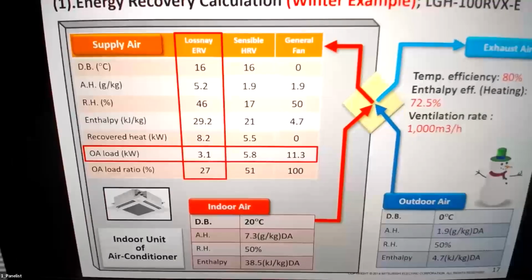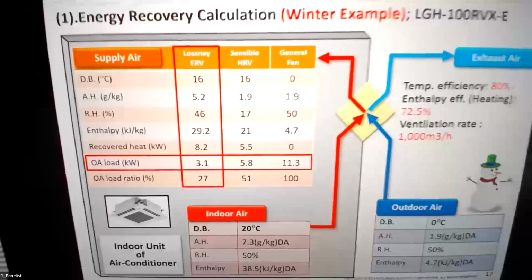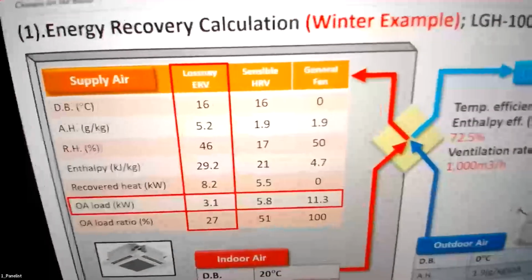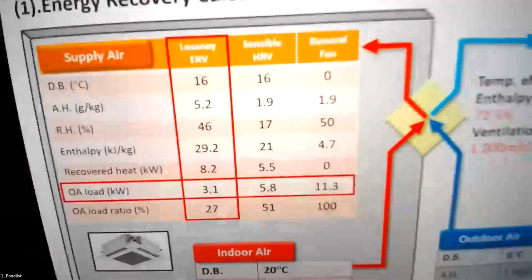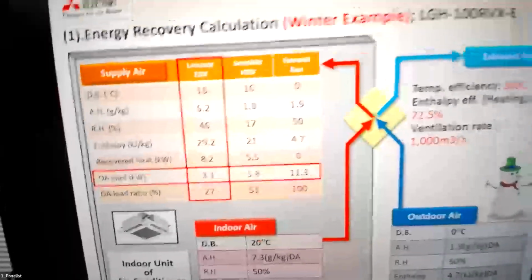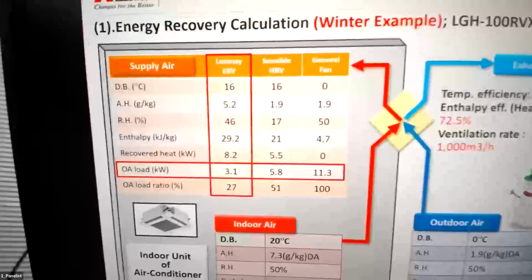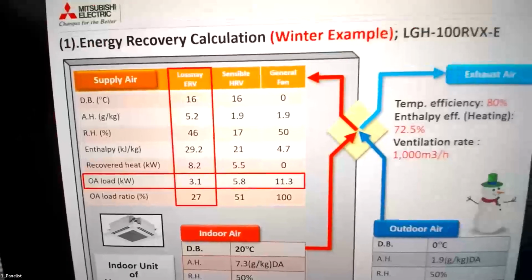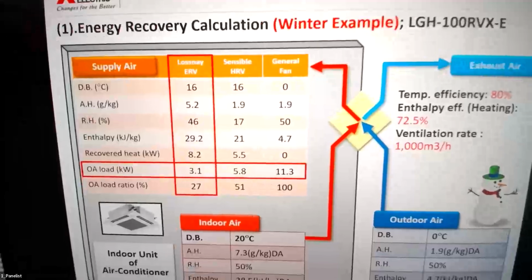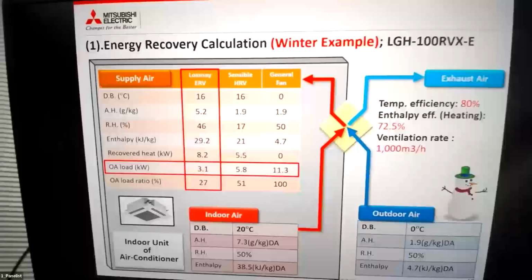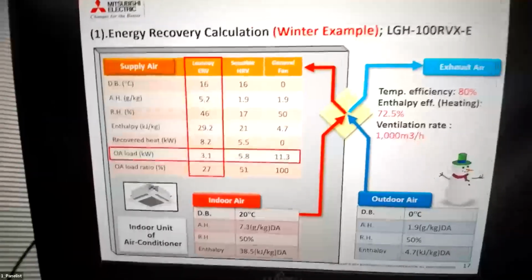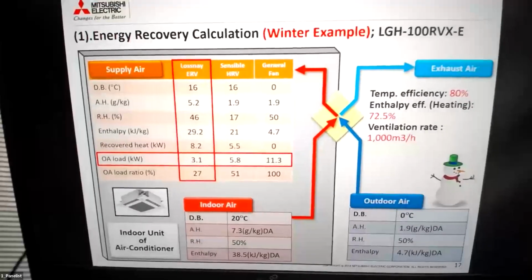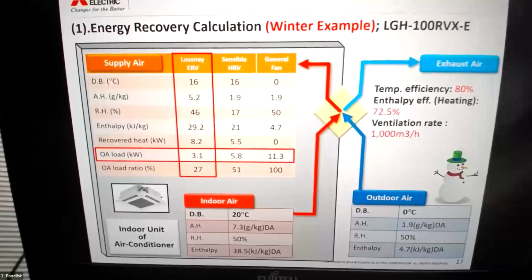Yeah, for operation for cold climates, the technology requires a defrost strategy. Does your technology have a defrost strategy? Very difficult, tough question. That's important. So, to be honest, let's say this Lossnay energy recovery ventilator can work at -10 Celsius without any problem. This kind of energy recovery we can expect.